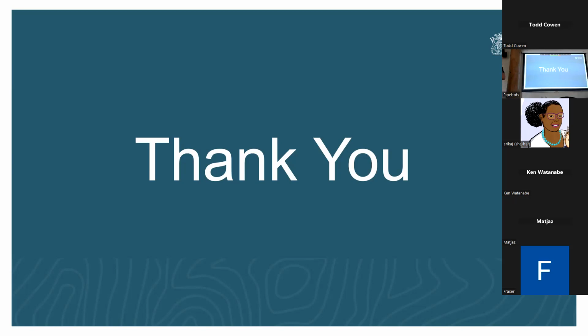Someone in the chat, James Bomhoff, asked, what has your experience been with alpha across a range of discharges? Do you decrease alpha as discharge increases or keep it static? Typically, we've found as the depth has increased, we're typically going to like 0.9, 0.91 of a surface alpha. So it's increased in that respect.